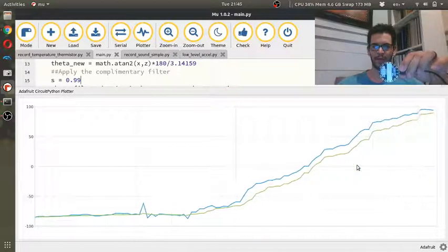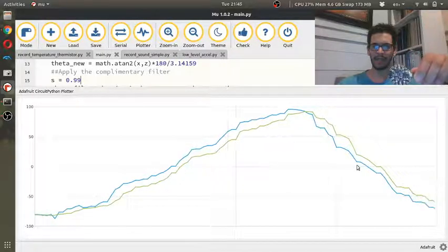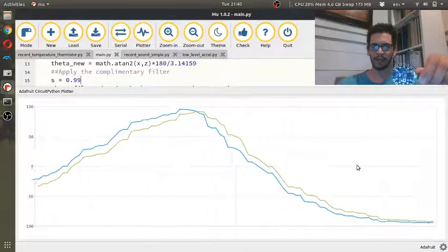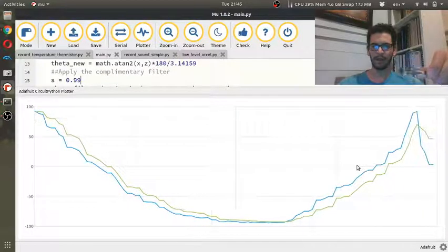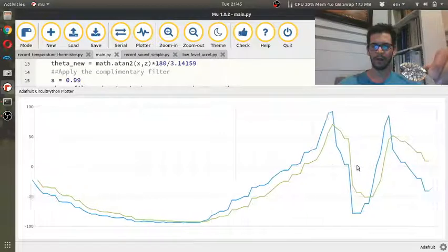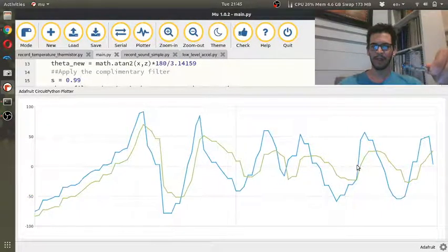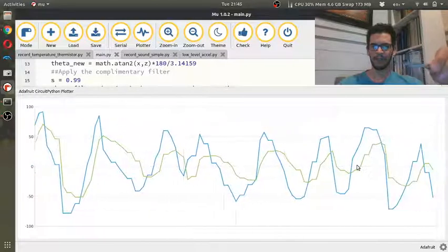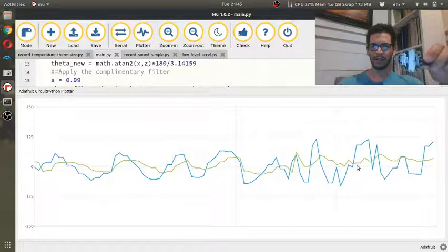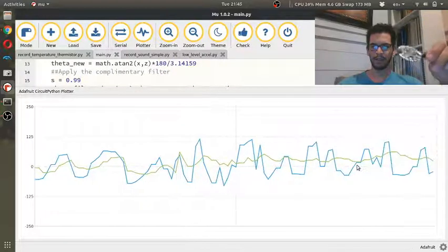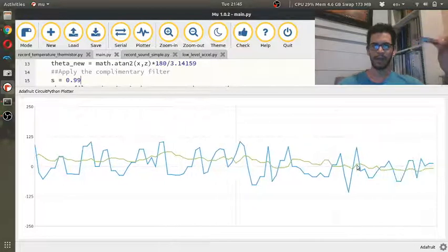If I put in a super low input frequency, the lag is maybe 3 degrees, and the magnitude is almost the same. Now if I increase the frequency, the magnitude is a lot different, and the phase lag is approaching 45 degrees. Eventually, if I go too high, I'm going to completely filter that signal out, and the green line is going to be almost flat.